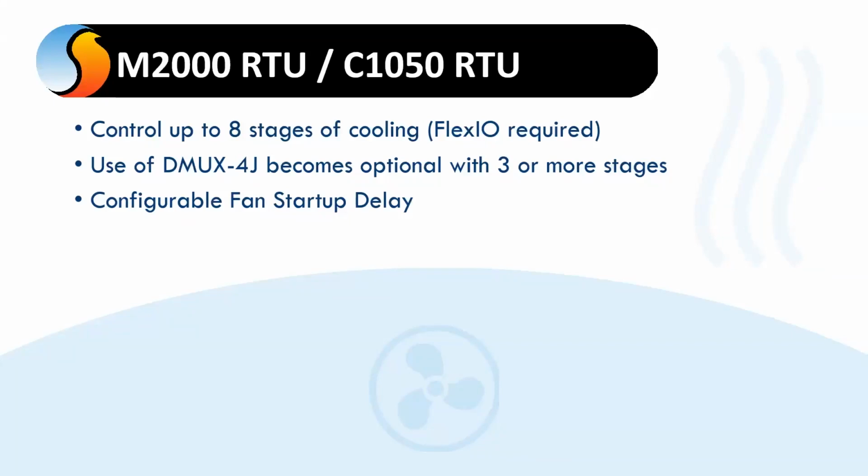We turn the fans on at the same time, so you have a hit with the surge of inrush current on the motors. Then everybody's compressor timer times out at exactly the same time, and all of your compressors slam on together, and you have a massive surge from all the inrush current combined of all those compressors.